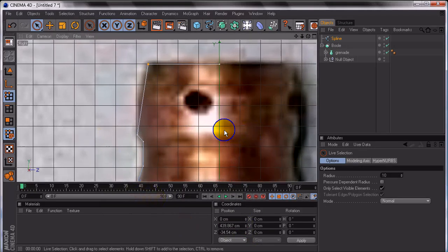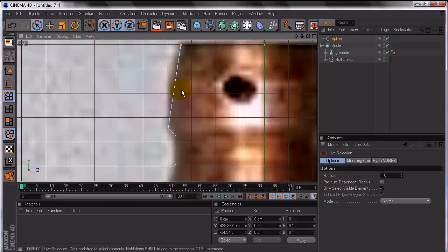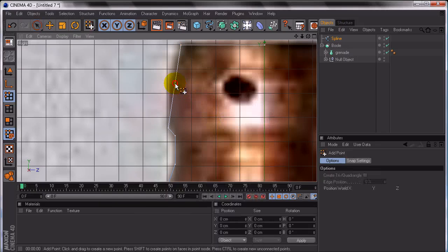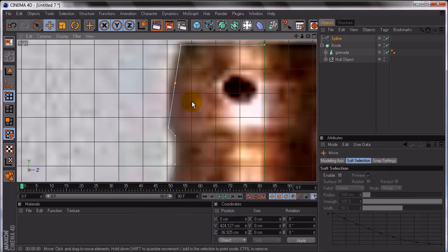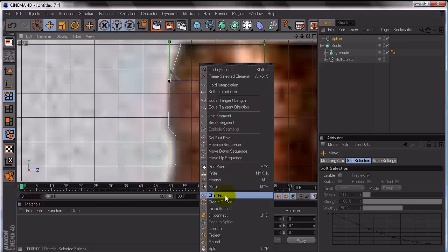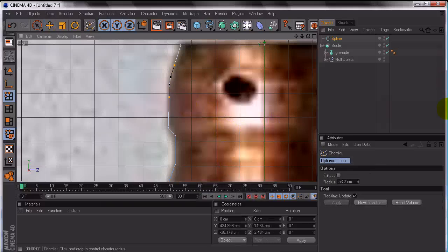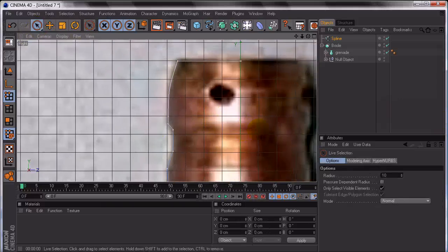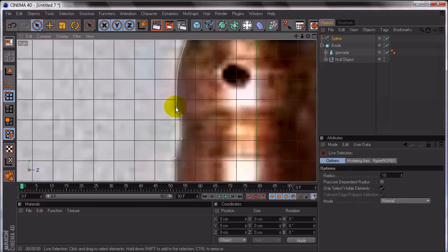To create the curve over here, we're going to add a point, press Alt-D to bring the gizmo back if you hit it while you were drawing it, and press E to use the move tool. Move it over, and then chamfer it. We could do it by hand using a Bezier, but that would affect the next point, and it would make this point seem less hard-edged, even if we move the Bezier point all the way to the center.